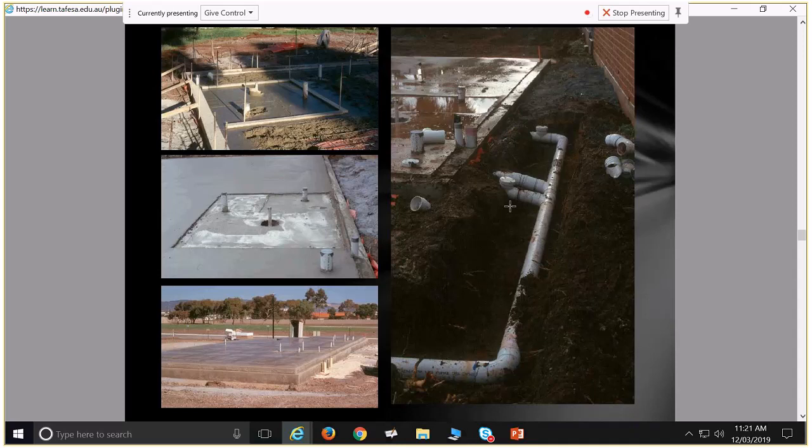And any floor water, if you don't have a floor trap in there, has to flow back to your shower. So if you're doing a tiny bathroom like this, yes, you can get away without doing a floor trap, because you can slope the whole bathroom area back to your shower.